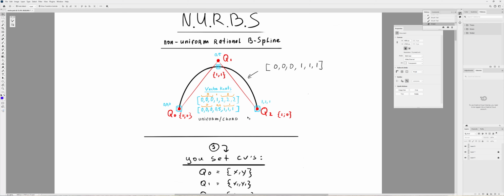But when you add additional separations using spans, basically transforming the vector knot from uniform to non-uniform, when there are really specific chunks, then uniform and chord define how these chunks will be presented in the vector knot. Because of that, they will define where these edit points, the beginning and the end of every span, will be placed on the curve through which the curve will be constructed.